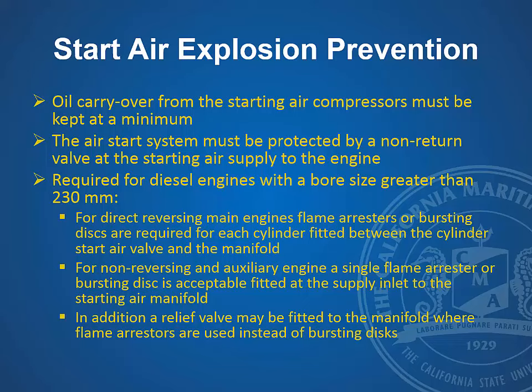For the direct reversing main engine, flame arrestors or bursting discs are required for each cylinder, fitted between the cylinder start air valve and the manifold. For non-reversing and auxiliary engines, a single flame arrestor or bursting disc is acceptable, fitted at the supply engine inlet to the start air manifold. In addition, a relief valve may be fitted to the manifold where flame arrestors are used instead of bursting discs.